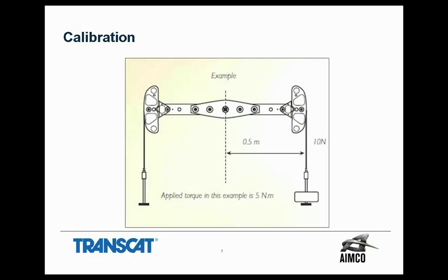When we're testing for torque, it's a very good idea that we have calibrated devices and calibrated transducers that we're using, so that we not only know that we're accurate, but that we are traceable. Some of the things to keep in mind when we're calibrating transducers are your length and mass standards and how you treat them. Your arm should be radius so that you don't change the length as you change the level of the length standard. You should pay attention to gravitational constants, especially if you have mobile labs. You have to know the gravitational constant in the area you're going in.